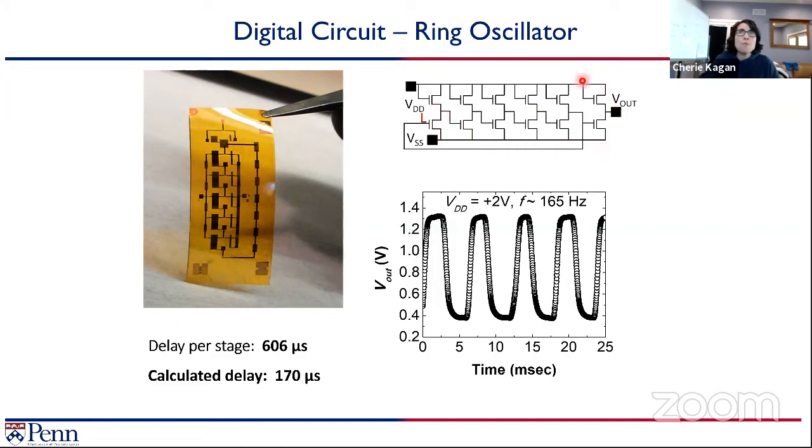And then there's one more stage that serves as a buffer to the electronics on the output. But I really want to focus on these five here to describe to you how the ring oscillator works. So for example, this is where it's operating as a switch. There are two extremes where a low voltage in will give you a high voltage out. So if I put on the input a low voltage, as you see here with this red L, what I should expect is that the inverter will give me a high voltage out.